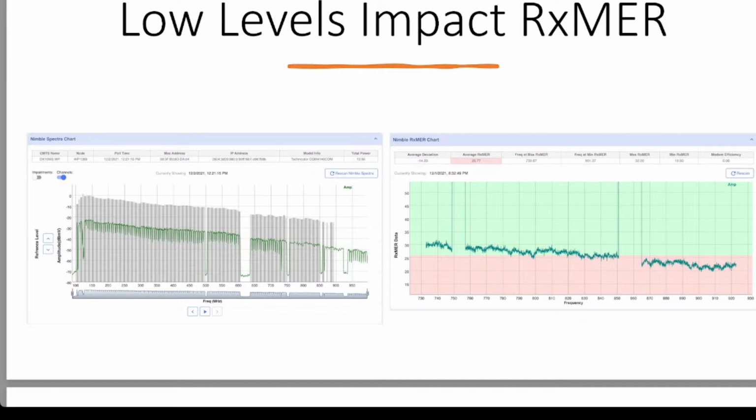We'd like to see minus 5 to plus 5. That's the ideal level for all channels in a downstream. We can go minus 10 to plus 10, but once you get out of that range, bad performance is going to be expected. The original DOCSIS 3.1 spec was minus 15 to plus 15, but you're playing with fire. It's going to get worse.